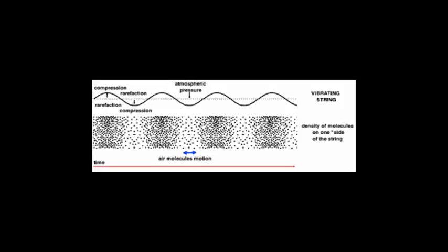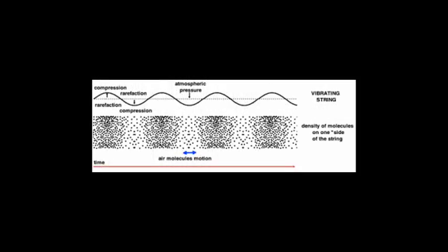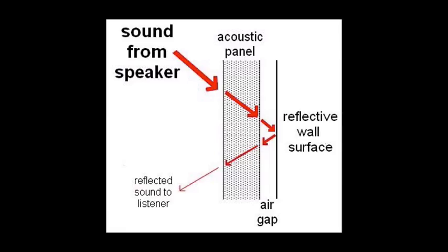You might be curious as to how reverb modulation works. If you listen to a natural reverberation, there is an element of randomness in the reflections due to how the molecules react to each other in space. While in a reverb unit, everything is calculated, and modulation helps to add an element of randomness to the reflections by adding another variable wave to the decaying sound. This wave will reflect off surfaces differently due to its changing pitch. Some reverb units have a modulation depth control, which controls how much you are able to change the pitch of the modulating wave.